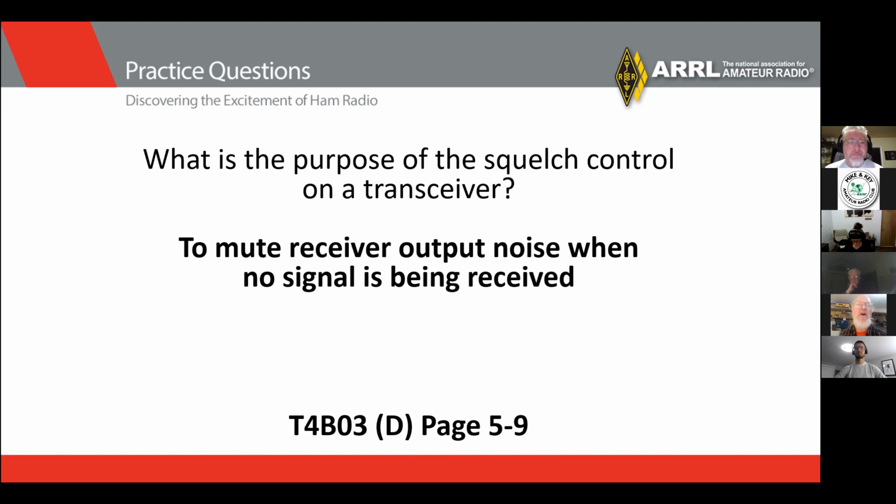So we turn the squelch up till it disappears. Just after it stops chirping at us, that's where you turn it up to. On this radio here, it's got an internal control 1, 2, 3, 4, 5 or automatic in the menu situation. Some actually have a knob you can turn, but it takes away that shh that's on the band all the time.